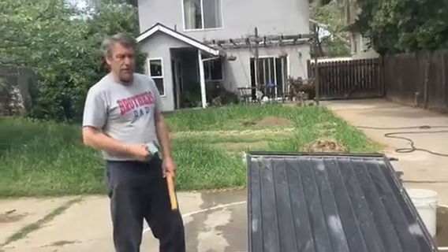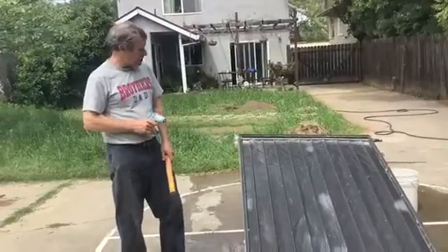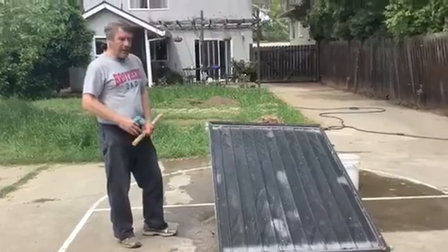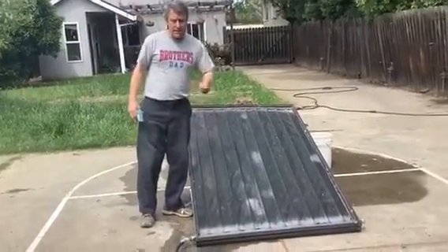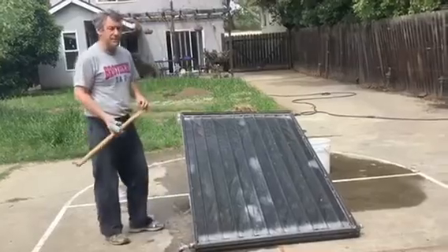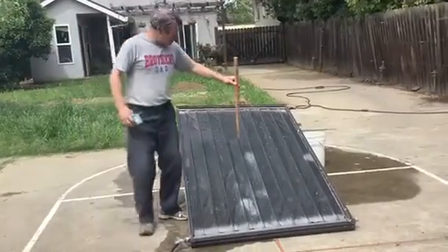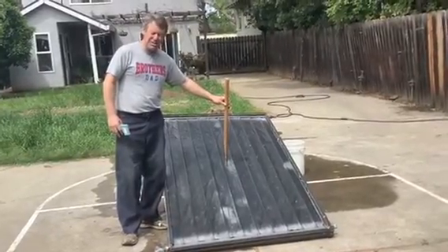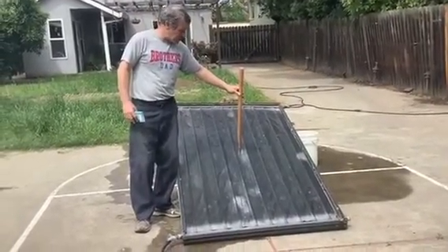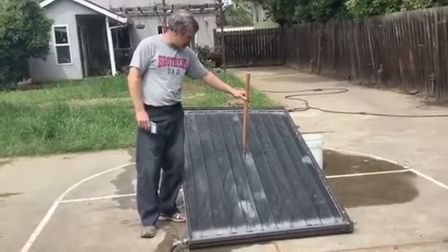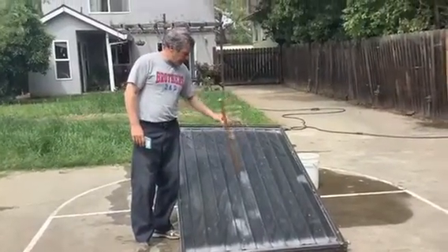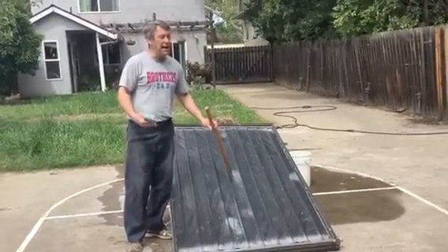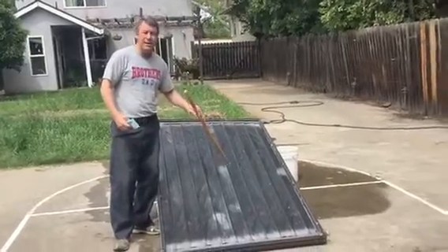Just really quickly, maybe try to visualize for yourself the angle of incidence. I'll give you a second to think about that. You might want to pause. What's the angle of incidence right now? Towards you guys, that's south, so I've got the azimuth of the collector to the south. Someone might say, wait a minute, this collector is facing up. That's the normal line. But it is the direction the collector is tilted towards, and this is tilted towards the sun, towards the south, so the azimuth is south. The sun is coming from over about here, so we have a pretty small angle of incidence. Another way of putting that, the sun is almost going directly into the collector.